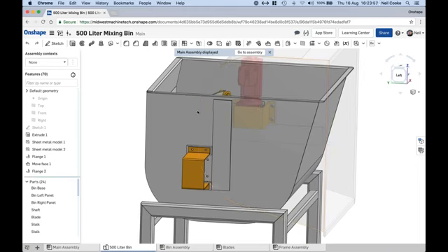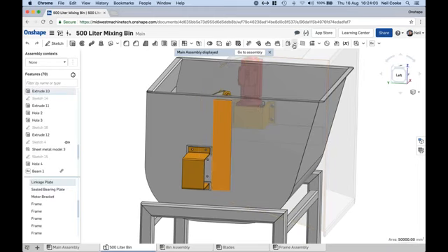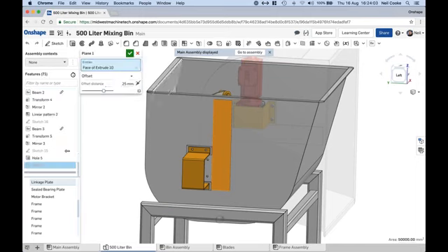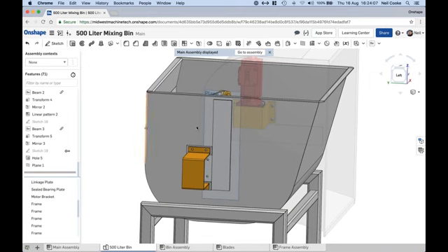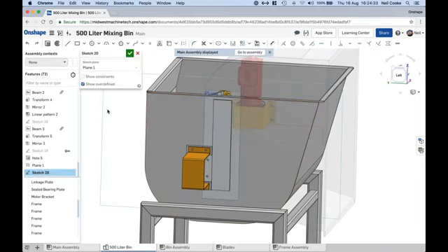Similar sort of thing. What I'll do now is I'm going to use a plane. I'm going to create a plane to sketch on through that face there. And the only reason I'm doing this is that if I didn't, then any sketch geometry I use to create the linkages would actually be split up by this face. And again, if you're a seasoned Onshape user, you would understand why that is. It's because of the sketch regions in Onshape, it's trying to decide for you which areas of that face should be used to extrude. But I don't want to include any areas of that face. So I'm just going to sketch on this plane here.